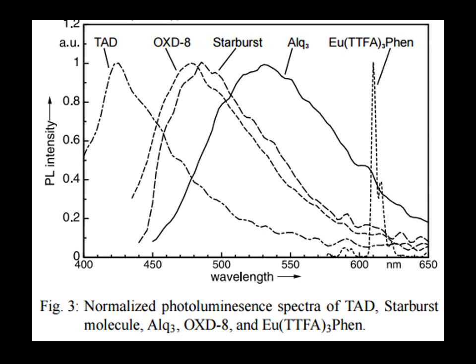Depending on the energy difference of the highest occupied orbital containing the hole and the lowest unoccupied orbital containing the electron, recombination of the two charged particles will emit a photon of varying wavelengths. This is similar to different photons emitted by different sized band gaps in semiconductor devices. Different colors can be achieved by adjusting the material based on its properties and energy differences in the molecular orbitals,